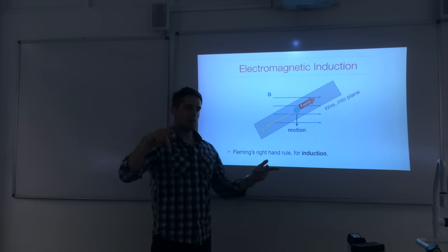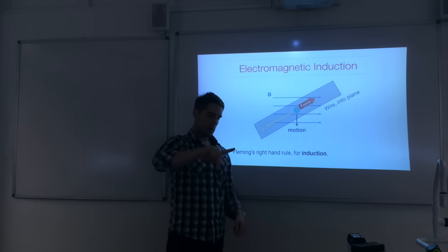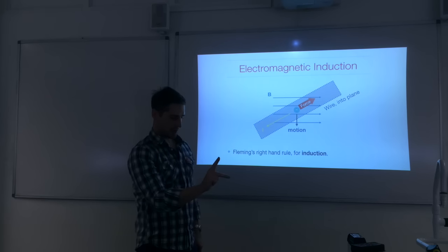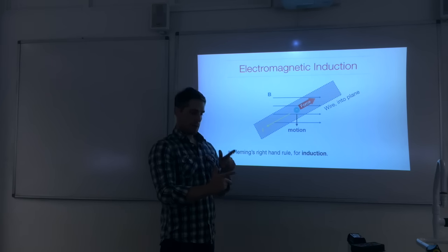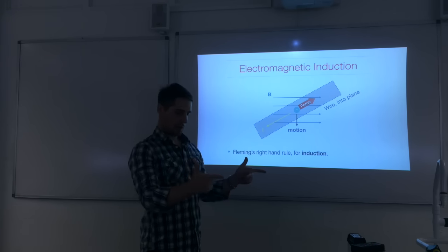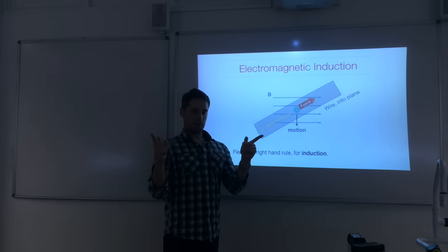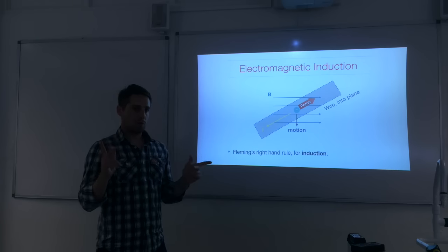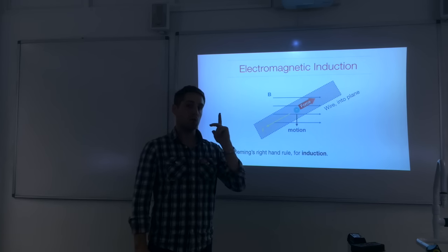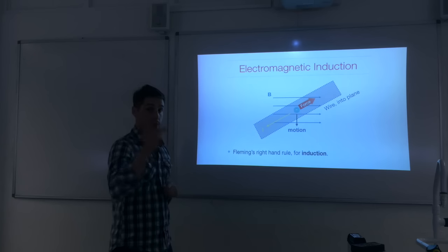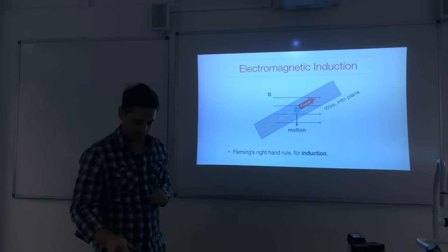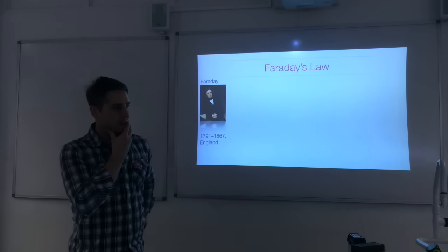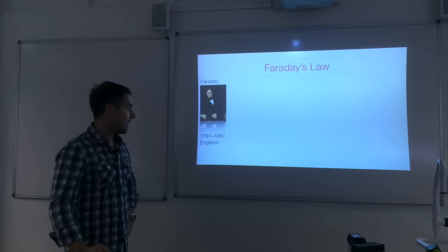Okay? So the same thing applies for Fleming's left-hand rule. You've got to have your thumb and two fingers all perpendicular to each other and move your hand around. Index fingers always point forwards, thumbs up, and second fingers are perpendicular to those. So this is Fleming's right-hand rule. Don't confuse it with Fleming's left-hand rule. This is for force on current carrying conductors. This is for electromagnetic induction. So that's how we can work out the current direction for a straight wire.